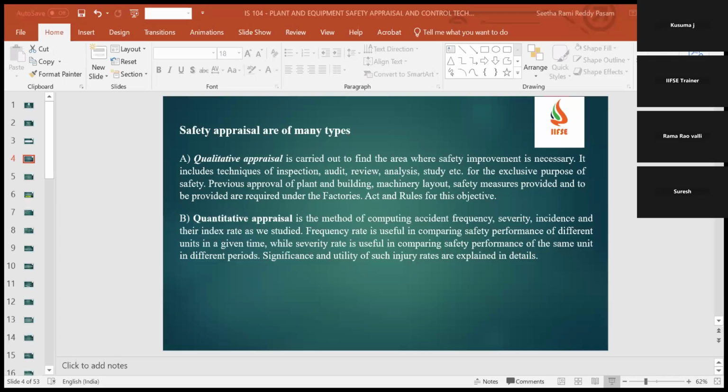One is plant safety sampling. We do safety surveys, fault analysis, risk analysis, hazard and HAZOP studies, even safety inventories, system safety, safety standards, safety permit system, safety tag and lockouts, and safety stewards. When you say safety stewards, we have standby persons and even fire watch and manhole watch, all of which come under safety stewards or safety representatives.